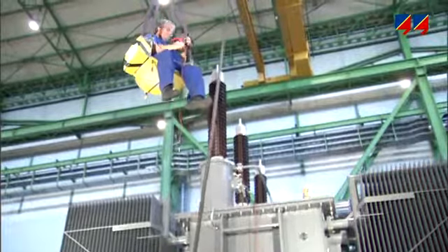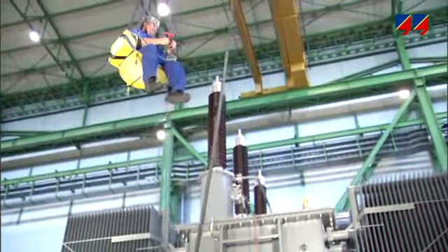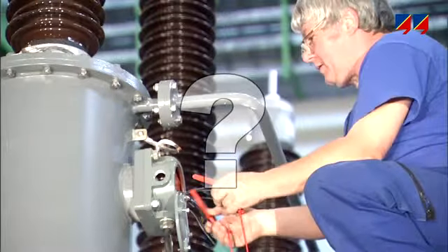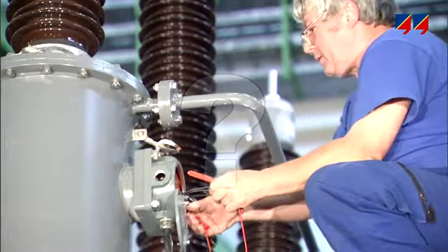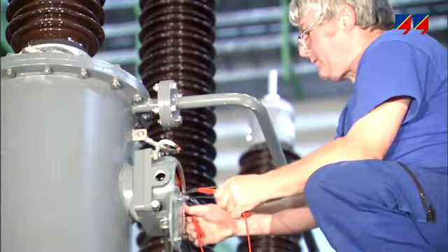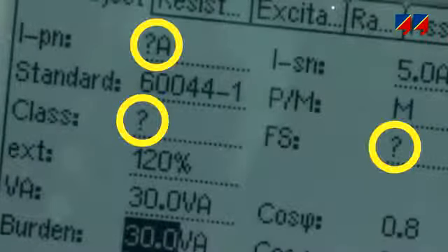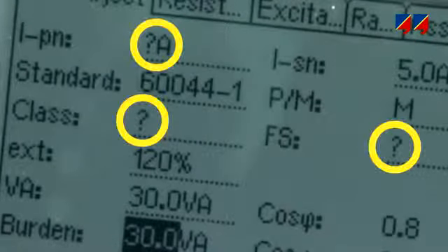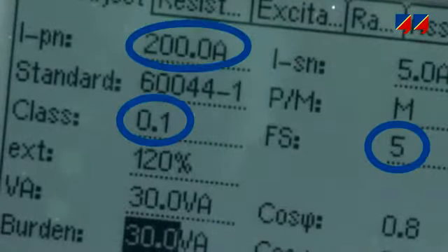Finally, CT Analyzer offers a unique function for guessing the characteristics of an unknown CT, for instance, when it is unclear which CT core or which CT tap is wired to a particular terminal. The user simply enters question marks for unknown parameters, and CT Analyzer will guess them.